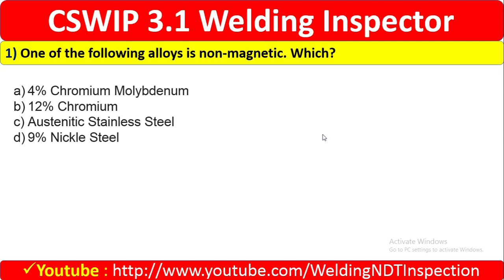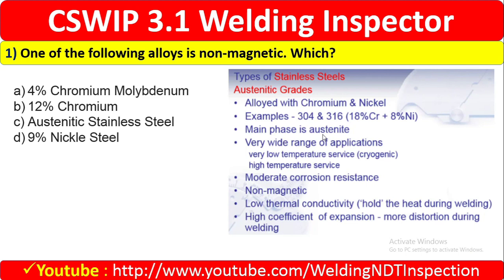For non-magnetic, you see here the type of stainless steel, austenitic grade. Alloys with chromium and nickel, for example 304 and 316, with 18% chromium plus 8% nickel. Main phase is austenitic. Very wide range of application. Very low temperature service, cryogenic.